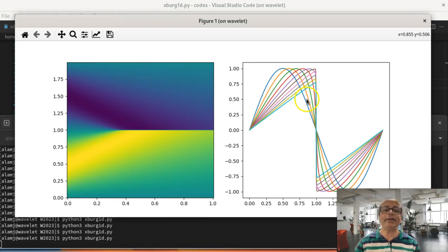Maybe in another lecture I will demonstrate, or maybe you can give it a try yourself looking at Burger's equation, but just take the finite difference method and the Euler method, and you can see a huge difference. With the same parameters, the value of the viscosity, the number of grid points, the time step and the time span that I have currently used, if you use the same parameters and use a finite difference method with an Euler time integration scheme, you can see that it is really difficult to control the numerical instability.